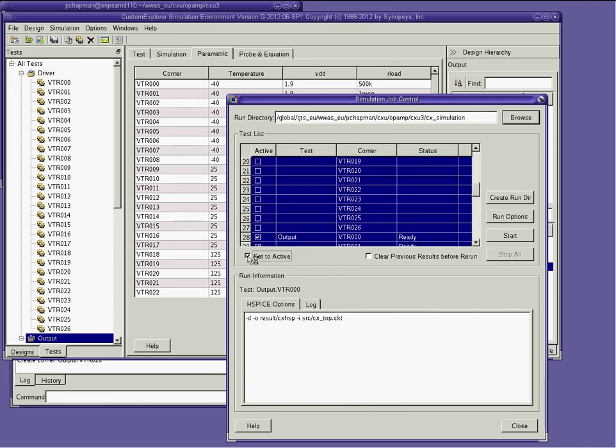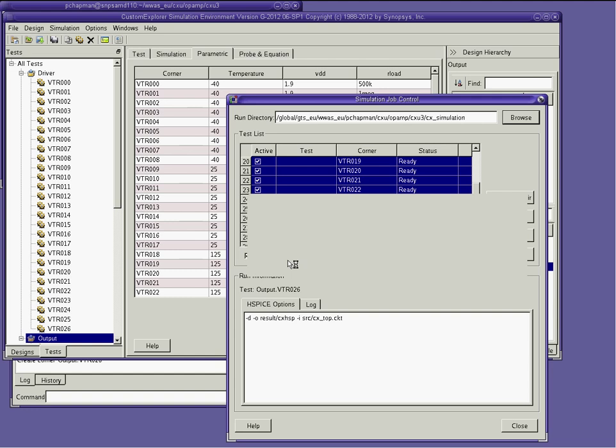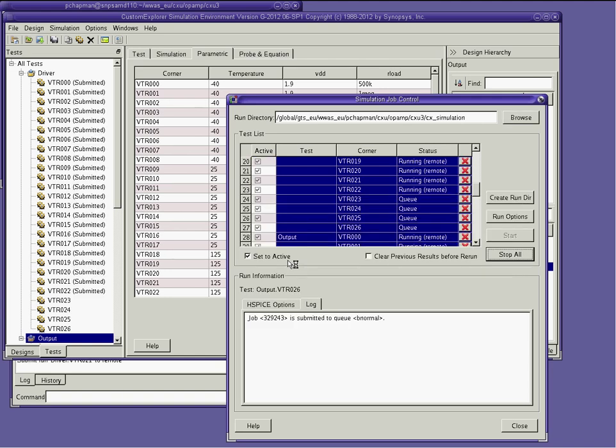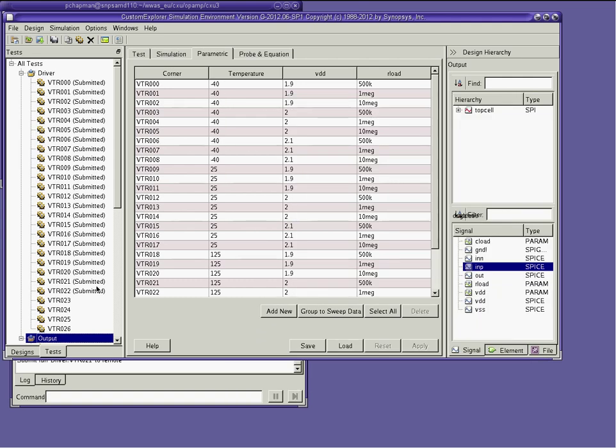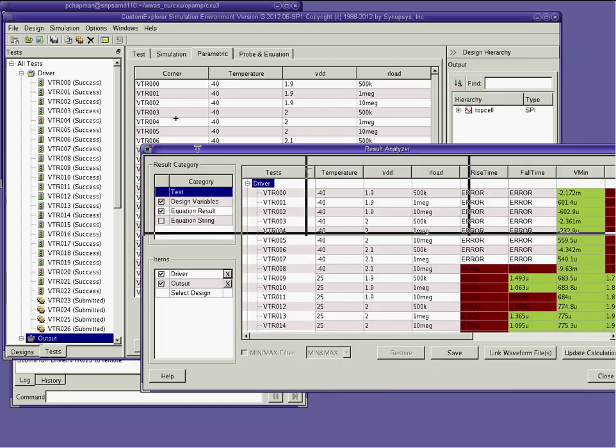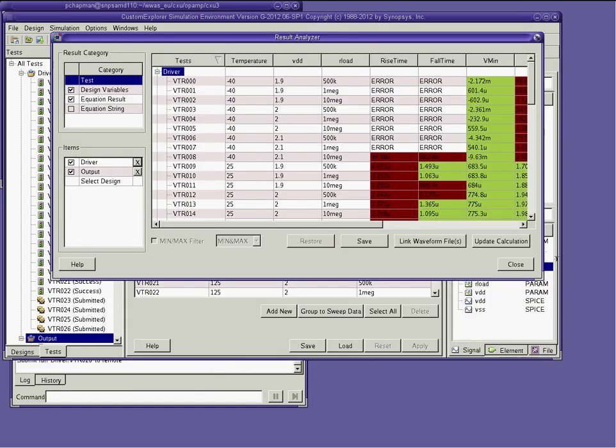So, critical purpose of a regression environment is to answer the question, does the design work? In order to do that, you need to build a whole set of measurements of some sort to verify whether it's doing what you want. In this case, as I'm looking at an output driver, what I'm going to say is I'd like a peak-to-peak measurement of my output signal, which I'll drop in there. This design has a 2-volt supply, so I'd like at least 1.8 volt swing out of it, and I'll be a bit surprised and concerned if the output goes above 2.2 volts.